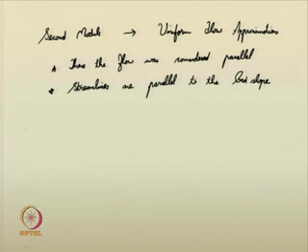Suppose a canal is being designed in such a way that you have to carry so and so amount of discharge regularly without any fluctuation, and after a certain time it becomes a uniform flow in that canal. So, such situations are very rare. In nature, a river cannot have uniform flow in every location, because the boundaries of the river are varying. Most rivers may not have a solid, non-erodible boundary. So, you may encounter varied types of flows.